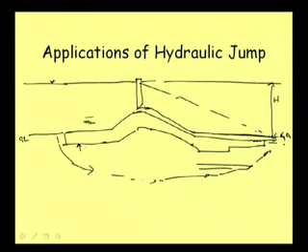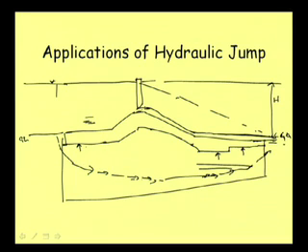That uplift pressure is equal to the depth of water here, and then when it is moving, of course, we use different formulas, like how the energy will be lost when the water is moving through the soil. Its existing energy will be lost, and this energy will gradually reduce, of course, but still it will have a substantial amount of energy, and then uplift pressure will depend on that remaining energy. Well, so the uplift pressure here will be more, and then here it will be like this, here suppose less, and then this is the energy loss in between, and then we are getting the uplift pressure like that.